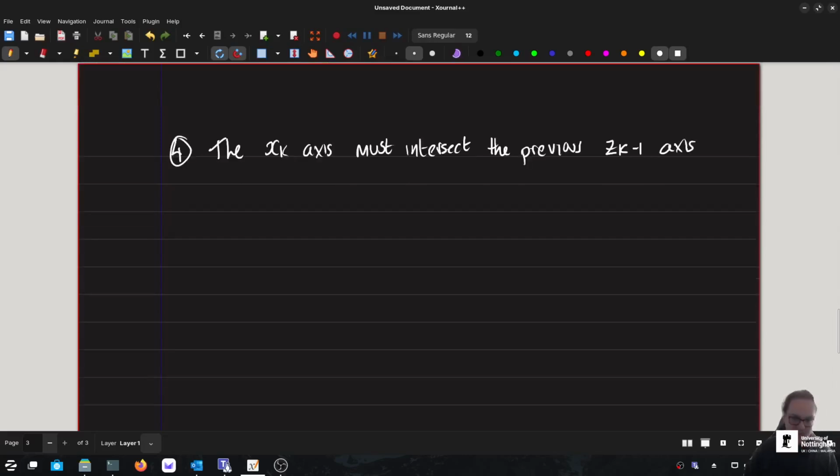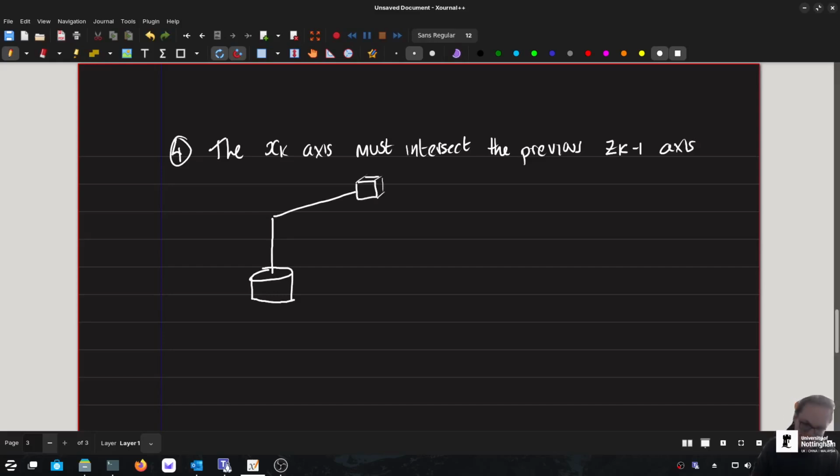Okay, so I've got another example here, so hopefully I can draw it properly. I've got quite a weird looking robot. It's a sort of cylindrical robot, not fully cylindrical. So I've got a rotary joint here. The link goes up, and then it goes into the page, or into the screen, I should say. And then I've got a prismatic joint, so that's often the distance, and it's got a link over here, and our end effector can be over here.